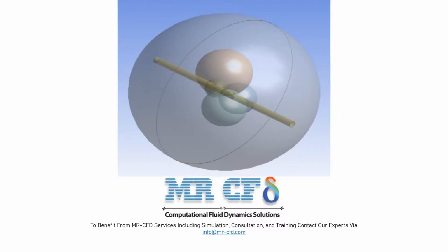The geometry of the present model is designed in Ansys Design Modeler software. The present model comprises a cylindrical tube as the capillary, 4 spherical blood vessels attached to the capillary as tumors, and a spherical space for intra-arterial blood flow around the vein, which has a slower flow rate than flow inside the capillaries. The spherical tissues around the capillary have a different radius. The outer sphere is also considered as the space for blood flow within the tissue and around the capillary, which contains 2 input and output hemispheres.